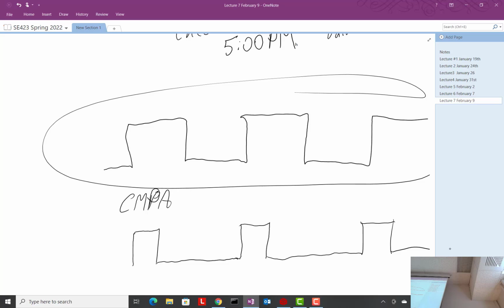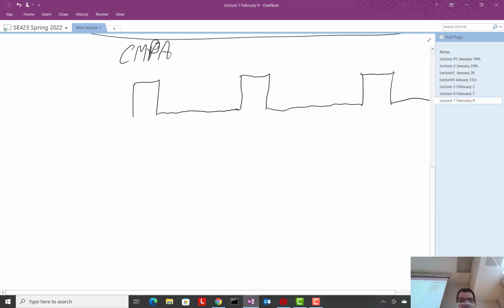The idea is you have to get this carrier frequency fast enough that the time constant of the motor, or whatever you're driving, filters out that idea or the step response. So it just sees it as a constant value. Okay, so it's like taking this signal through... you would have to play with this.